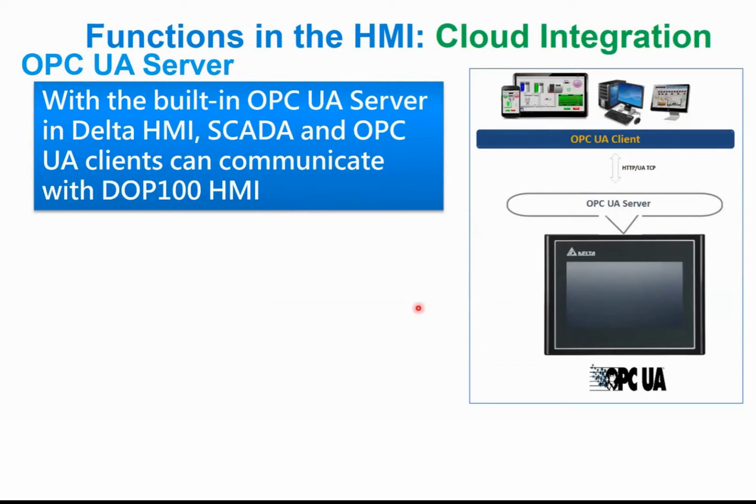Maybe you have a pump, different kinds of applications, different kinds of controllers. They are connected to this HMI, and you want to control them. Then you just use this OPC, which is TCP based, to connect to those SCADA clients or OPC clients. Then you can control all the devices on the HMI. So that's for the HMI. This is just an introduction about our HMI.